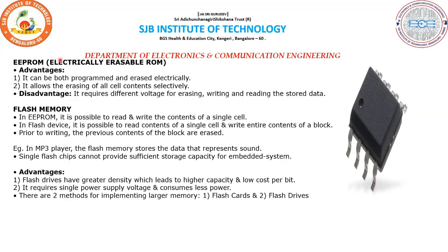So EEPROM, electrically erasable ROM. What is the advantage? It can be both programmed and erased electrically. It allows the erasing of cell contents selectively. What is the disadvantage? It requires different voltages for erasing, writing and reading the stored data.